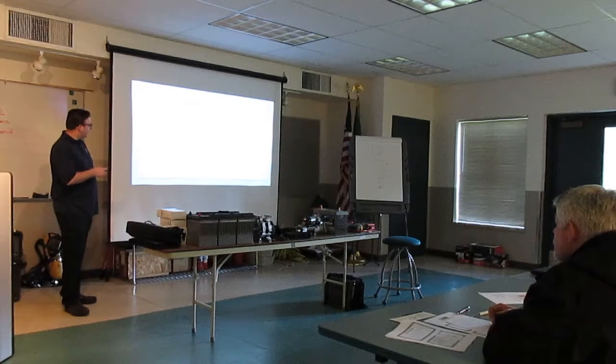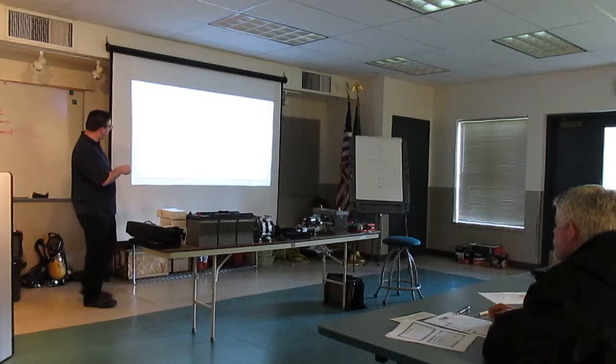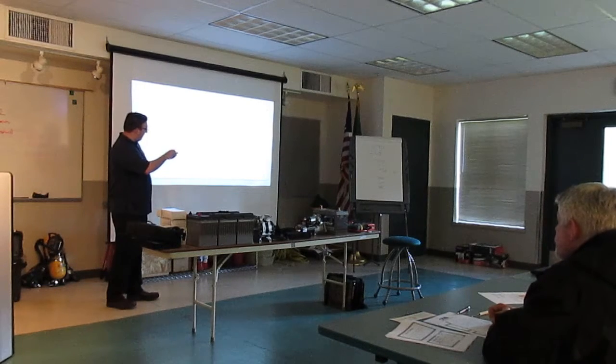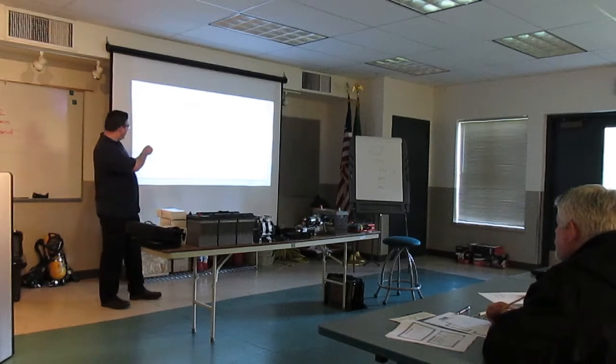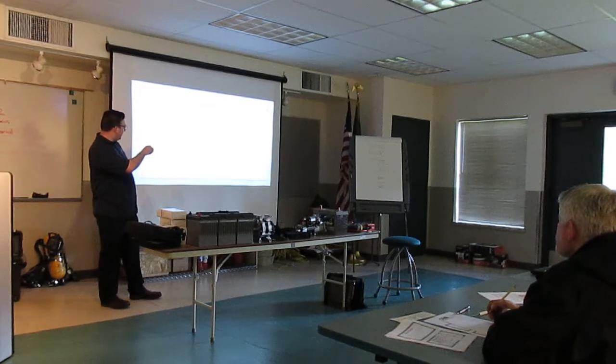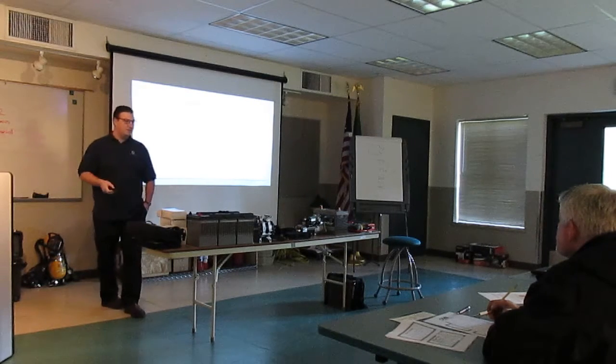Now here's a manual charging profile. We have 12 down here for our voltage, high of 17. Then we have our current, right? So our voltage is at 14.5, steady going across. And as our voltage rises a little bit, our current drops down, because as the batteries get to their full state of charge, they don't take as much current going in.